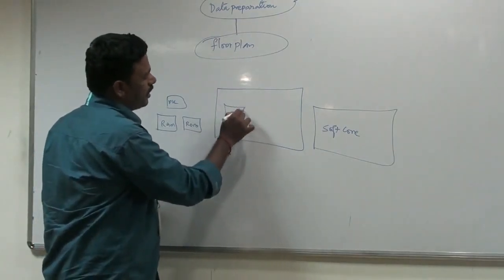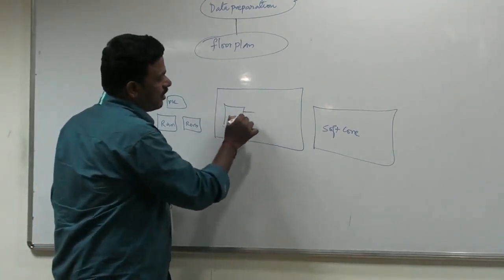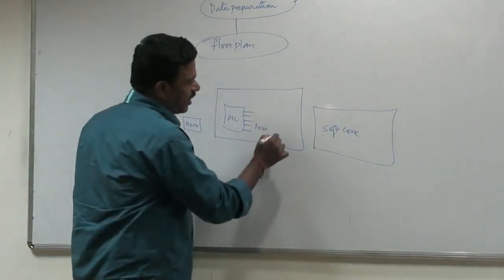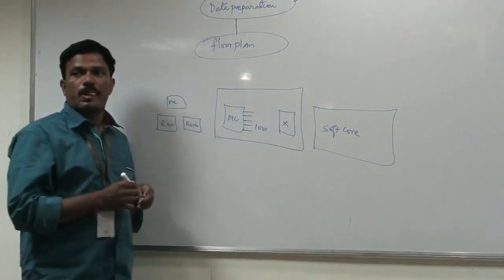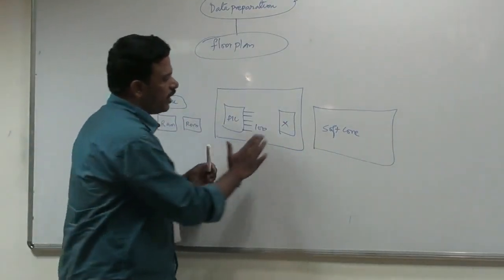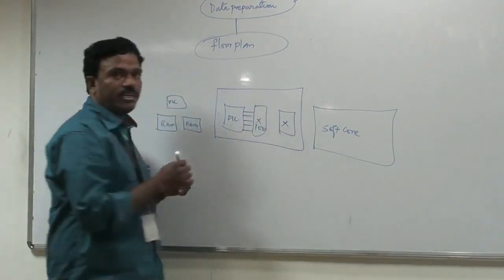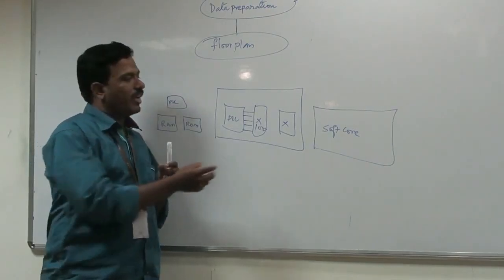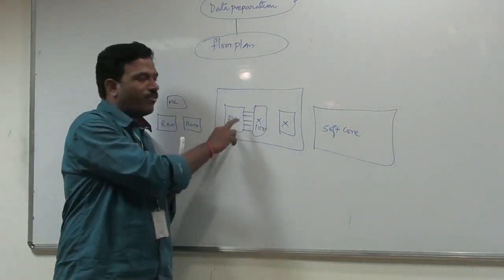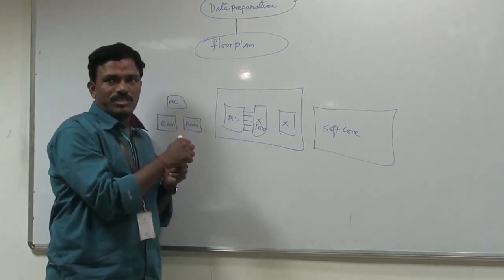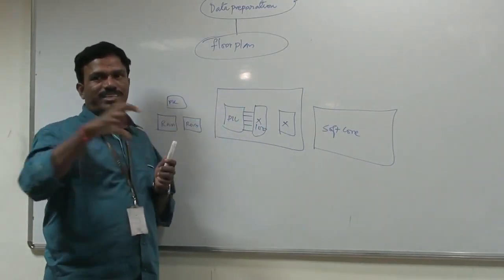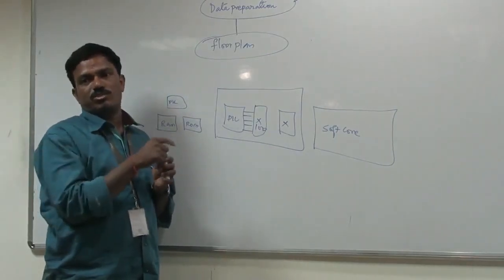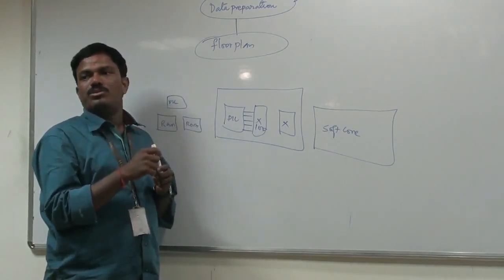And also while placing the macros, right? Suppose I am just having PLL. This PLL is having 100 interconnections. This 100 interconnections speaks with X module. Then what I have to do is I need to keep this X very close to this PLL so that my interconnect delay will be less. Is it correct? So when I place this X very close to this PLL, if both this PLL and X speak together, keep this module together so that your interconnect delay becomes less, the timing will be improved. Right? That is also one important step we have to take care.